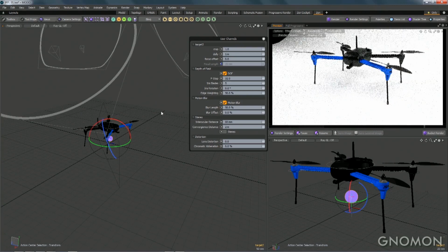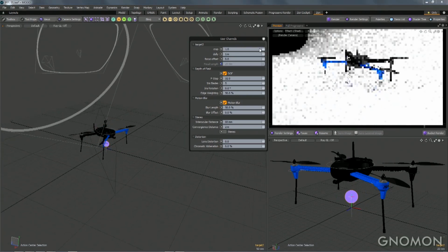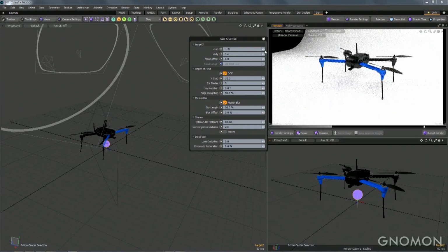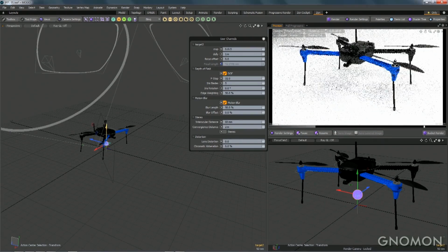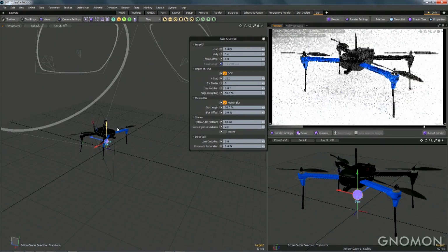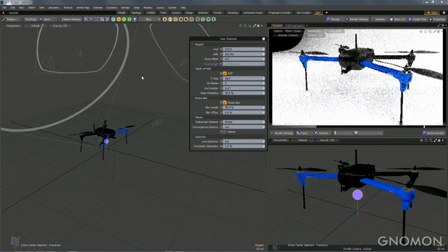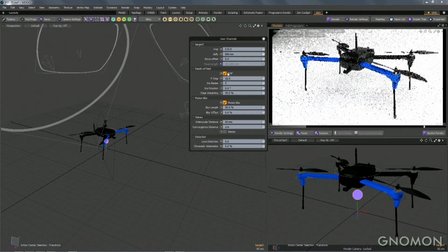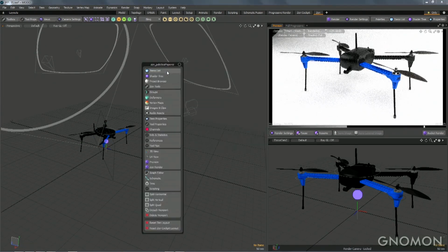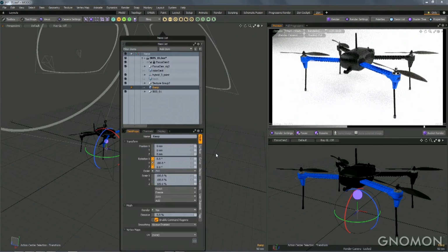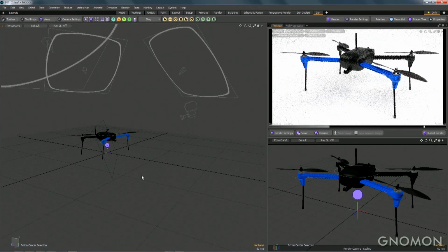My job is not to give you vertigo, but the point is, I give you a crop control that's just going to crop the image in and out. That's what I'm showing you here. And then I also give you a dolly control. And when you change the dolly, it simultaneously changes the focal length of the lens so that you can actually animate between a very flat perspective and a very dramatic perspective in a single smooth motion. So this camera I probably use for 90% of my animated shots because it is much more controllable for that kind of thing.